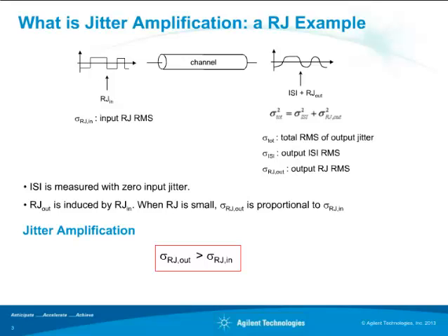So a question here from Harry. From the other direction, if I over-equalize the channel loss, can you attenuate the jitter? In theory, it's possible. Yeah. Wouldn't the upper sideband get boosted though? I'm not sure. Yeah. You have to be careful just to boost the carrier, not the sideband, right? Yeah. Either slope could kill you. I guess in principle you could do it. So you have to design your equalizer carefully. Yeah, it would have to just boost the carrier, not the sideband.